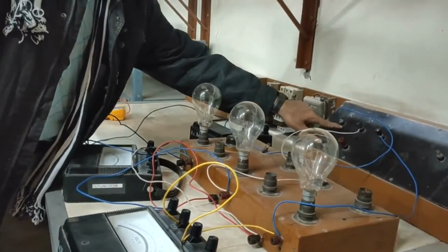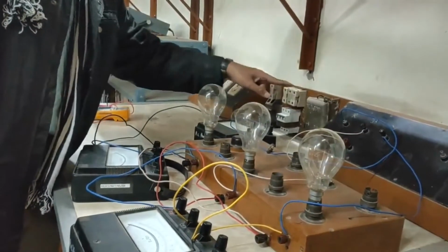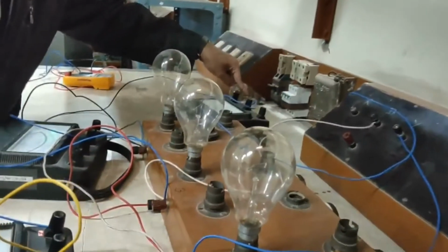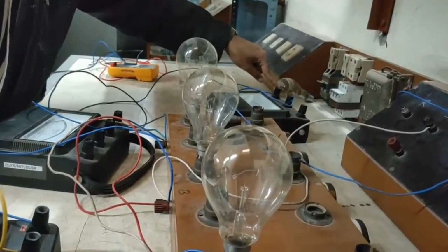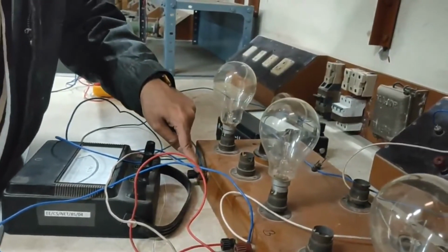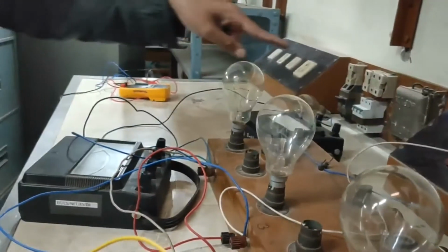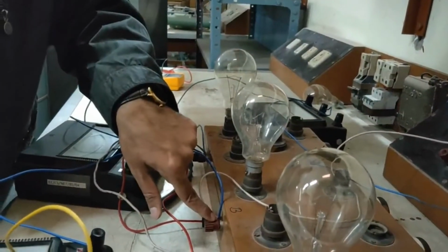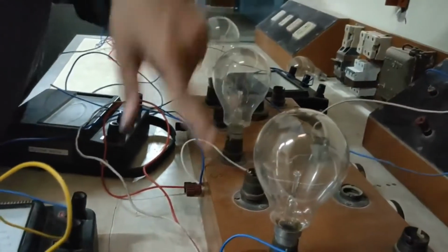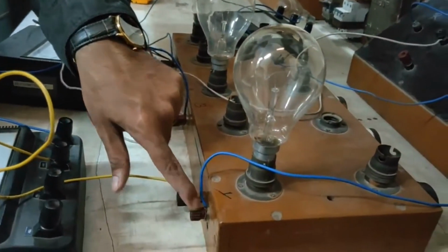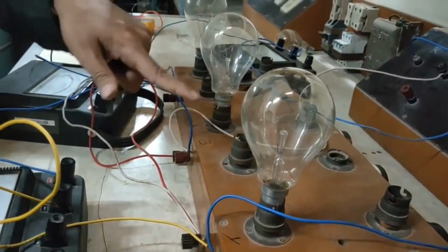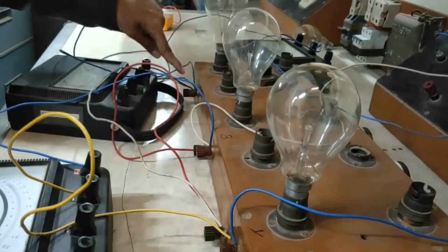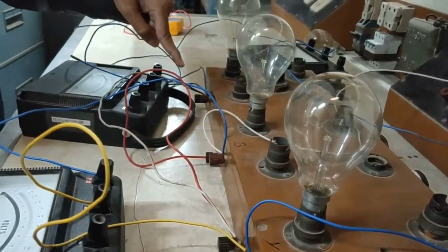These are the 3 supply terminals R, Y and B, and from these supply terminals, R comes to an ammeter terminal. From the other terminal of this ammeter, this gets connected to the terminal R1 of the load. Now from B terminal of the supply, a wire connects directly to the terminal B1, and similarly from Y, we directly connect Y1 of the load terminal. Now this load is to be connected in star, which is why the points Y2, B2 and R2 are all shorted to form the neutral point.